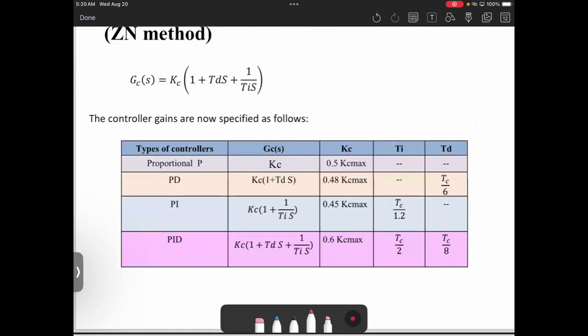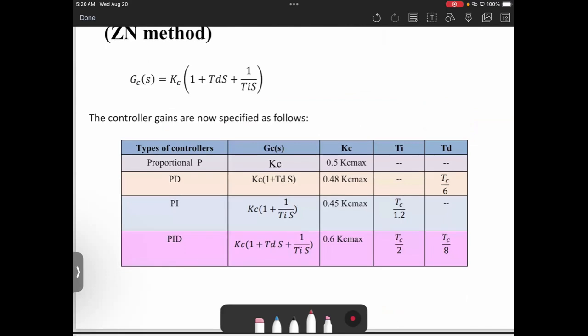Okay, so this is the same thing, but using a different notation or different transfer function. This is called the practical transfer function, the other one being the theoretical transfer function for the PID controller. Okay, all good? Clear? Keep in mind here, they sometimes call PCR as TCR, or TC. Just for your information, if you don't know what TC is, it's the same as PCR, P critical, but in different notation. Okay, does this make sense?